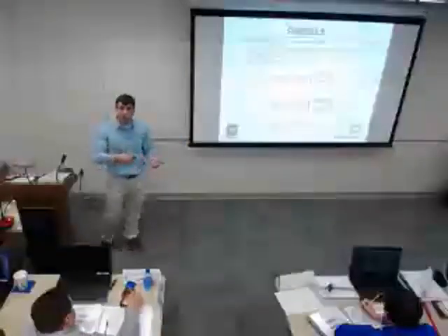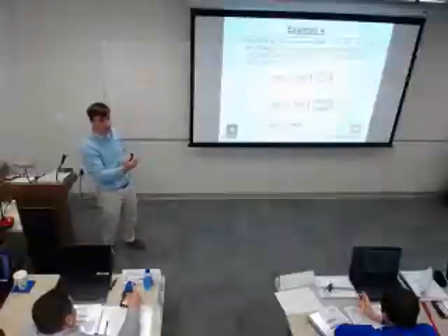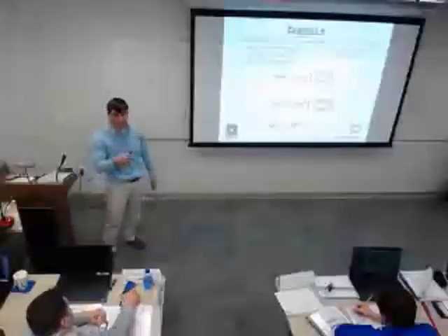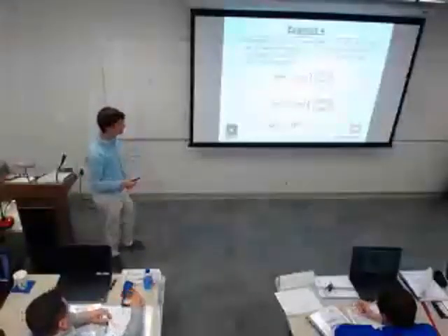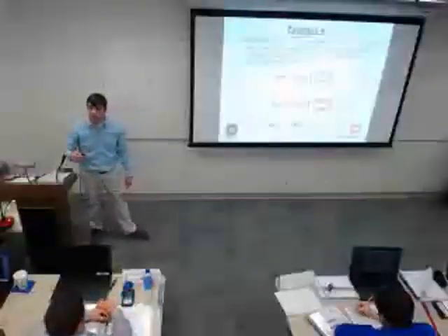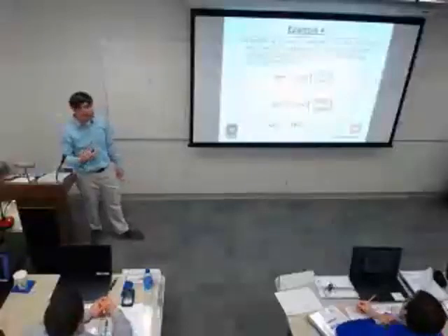Think back to our fan curve where we were talking. That's certainly in range of the fan curve we were looking at. We were right around that 1200, 1300 RPM range at the operating point we were looking at. So I need to make that change. I can do that either with a change in the sheave size, or if I have a VFD, speeding up or slowing down the VFD.